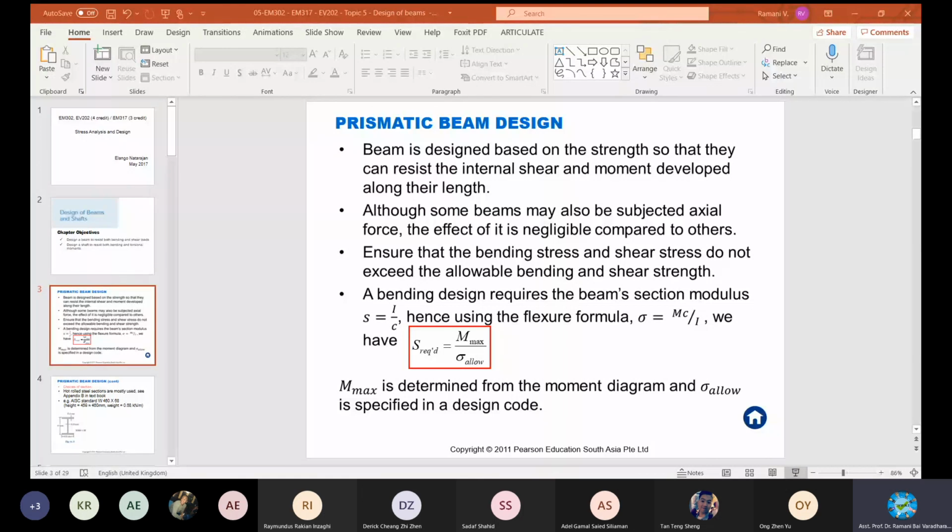Right. That's why, if you're asked to find out the shear stress, determine it at the fasteners first and then for the whole member itself.